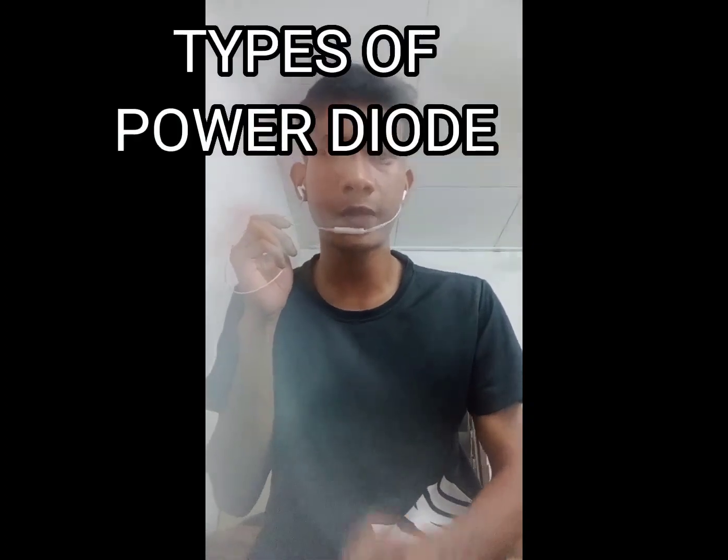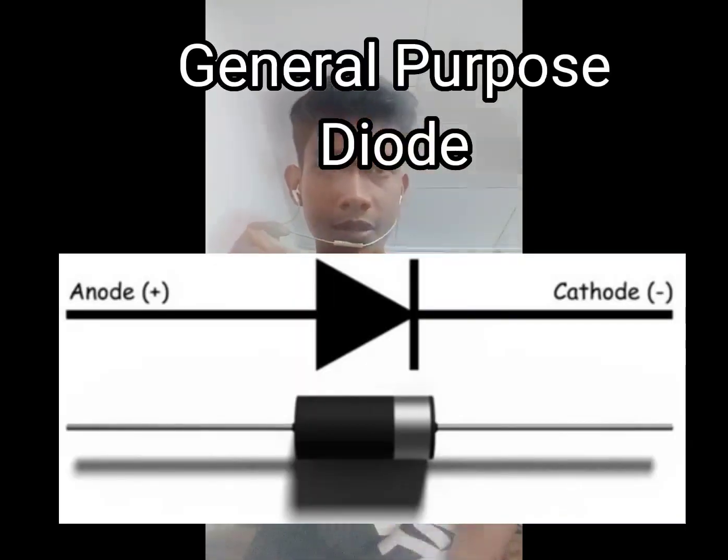Let's go to types of power diode. The classification of these diodes can be done based on reverse recovery time, the process of manufacturing, and depletion region penetration in reverse bias condition. The power diodes depending on the reverse recovery time as well as the process of manufacturing are classified into three types: general purpose diodes, fast recovery diodes, and Schottky diodes.